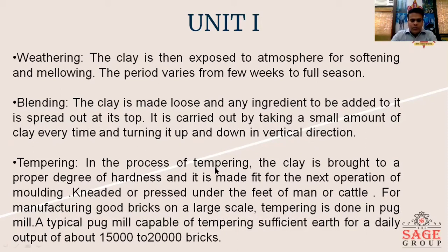Tempering is the next process. The clay is brought to the proper degree of hardness and made fit for the next operation of molding, by kneading or pressing under the feet of men or cattle. That means the kneading process is done so that all the layers and all the materials can be thoroughly mixed up. For manufacturing good bricks on a large scale, tempering is done by a pug mill.